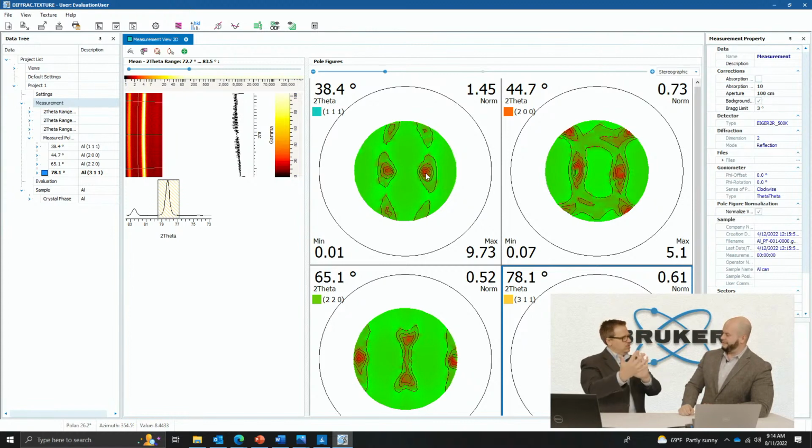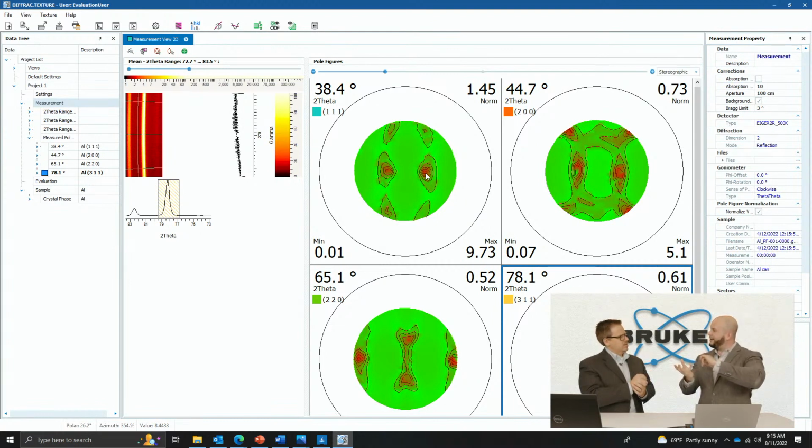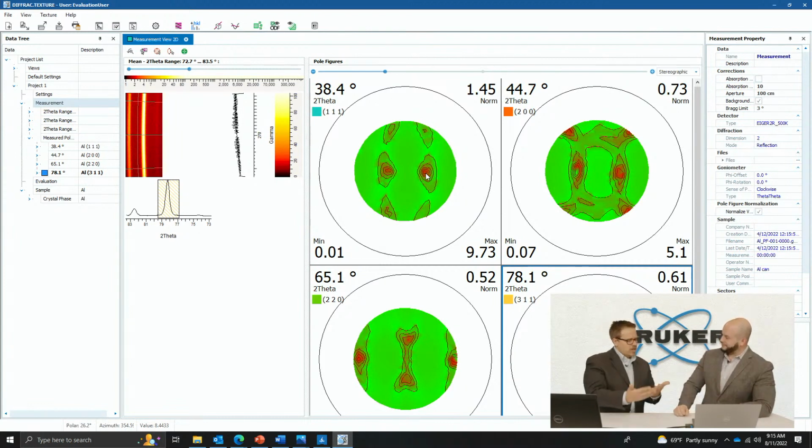So we have this cube, face-centered, so it has an atom in each face and an atom in each corner. So 1, 1, 1 would be which plane? It would be the plane that corresponds to, essentially you can imagine you have this cube, and if you put on X, Y, and Z, a point on X equals 1, Y equals 1, and Z equals 1, connecting all of them. So kind of this body diagonal. Exactly. And then if we had something like a 100, that would actually be the face. Exactly.